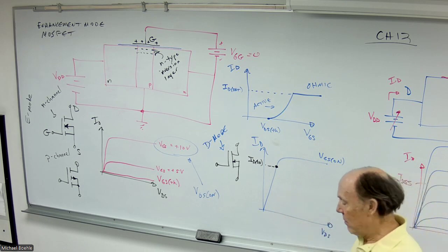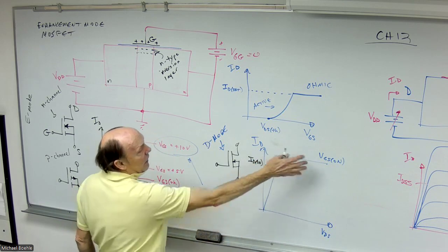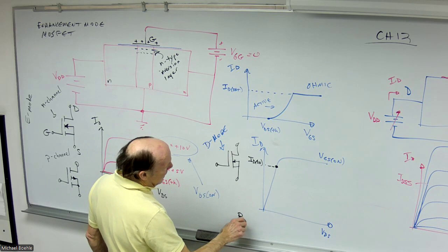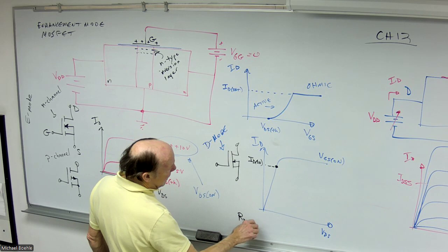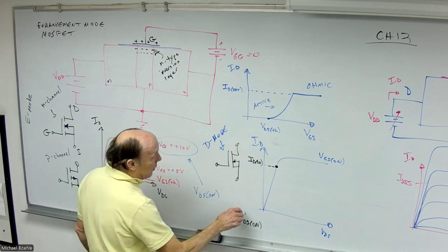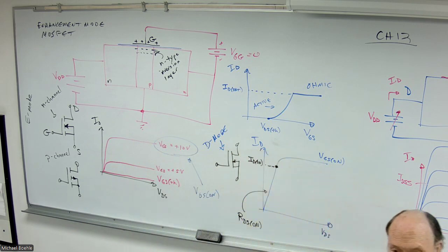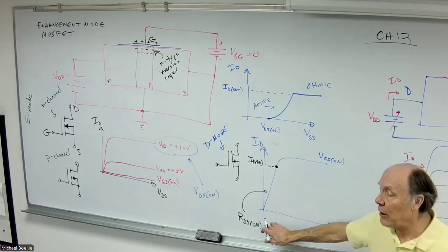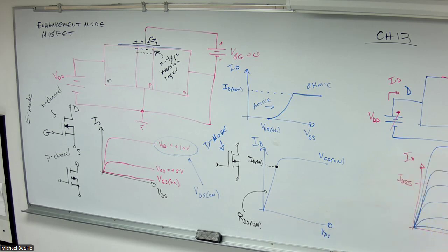In addition to this, for these values, the manufacturer will also usually give you an RDS on resistance, which corresponds to that curve. For a lot of MOSFETs, this is a fairly low number. Few ohms, sometimes even less.